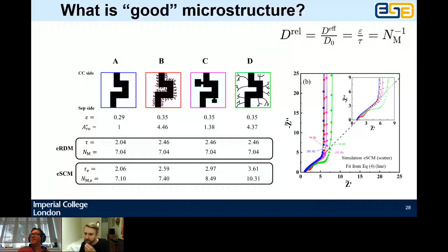Emiliano: Sorry if you spoke about this in your presentation, but I didn't follow all because I was answering questions. What about the kinetics of formation of the double layer, the impacts on the impedance spectra? Also, regarding the effect of the electrode thickness, do you think there is any impact on the tortuosity? So, good questions. Our double layer is just a capacitor, right? It's a very simplified model, and that's a speed issue. We just want to keep it a simple model to try and extract this as a singular parameter that looks like this transmission line.